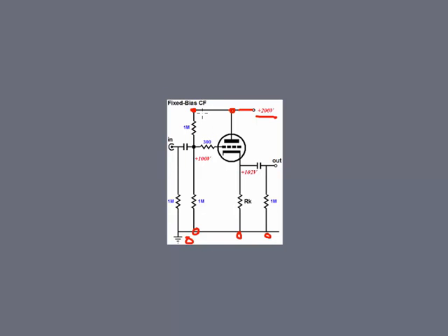So you just have to take this leap of faith with me. For the most part, all the voltage gets dropped across here, right? And the current would flow through here, right? Well, then we could use the voltage divider law. If you did the math on a 1 meg resistor and a 1 meg resistor, you add those two together, you get 2 meg of resistance. You divide 200 volts by 2 meg of resistance, you get the current, then you start multiplying the current times the resistance. What you would find out is that across this resistor, 100 volts gets dropped and 100 volts gets dropped across this one, leaving, guess what?